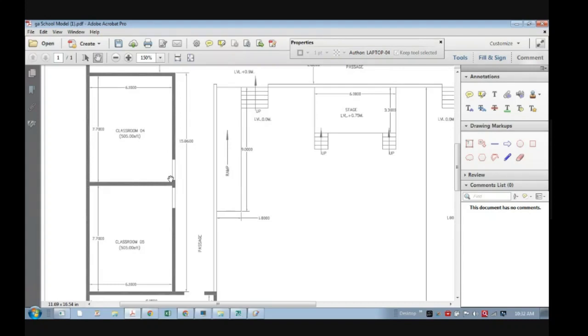Column would be better, because generally if there is a wall, having a column at the end of the wall is recommended, because we will provide one beam over here which will rest on the column directly. So generally I will recommend to have a column in this zone. At the end of all walls, mostly I am saying, not always, there has to be a column.